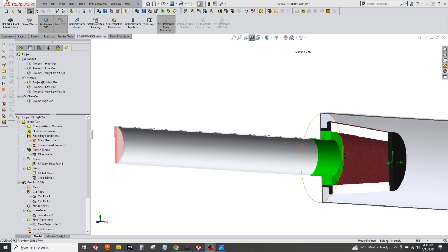Now, if we're talking about external flow, so if you think about air going over a car, there's a lot of examples where vortex generators can do you a lot of favors. A good example is the canards on the front of a car. These create massive vortices. If you think of a Formula One car's front wing, massive vortices coming off these things, and you can use those to your advantage. A more commonplace example that you might be familiar with would be a golf ball.